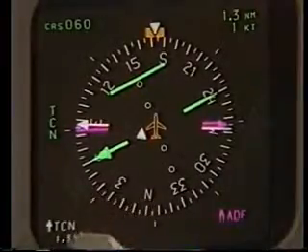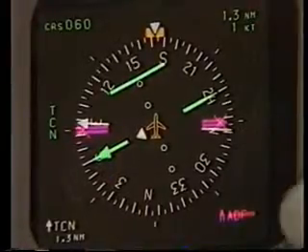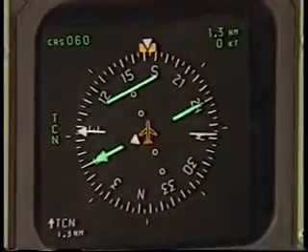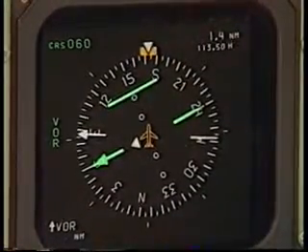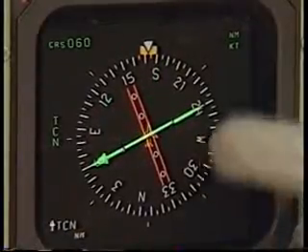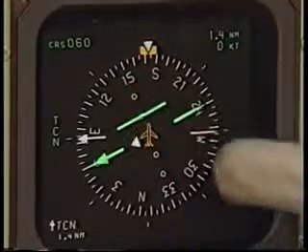If, say, the NDB goes off the air, then the red crosses at each end will cover the pointer to show that it is unreliable. If the TACAN now goes off the air, the indications change. Notice that the white needle disappears completely, and the red bars through the CDI tell you that the nav source for the CDI is unreliable.